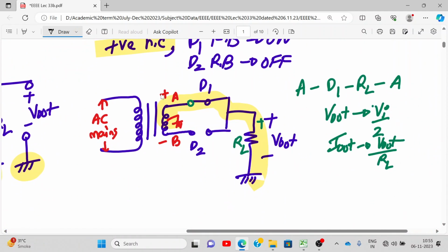when the diode D1 is on, look carefully, what is the voltage across the diode D1? 0. But when the diode D1 is on, what about the diode D2? What about the voltage over here? This is negative, not positive. So the reverse of Vi is connected over there, which means across the diode D2 a negative voltage is appearing, not positive.